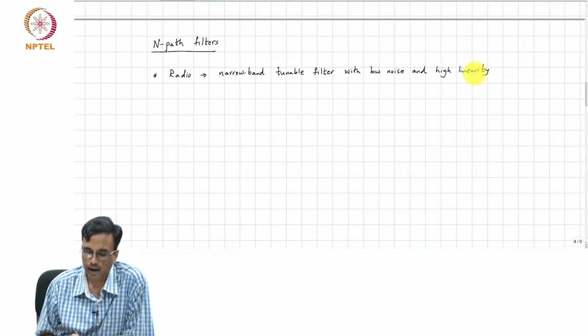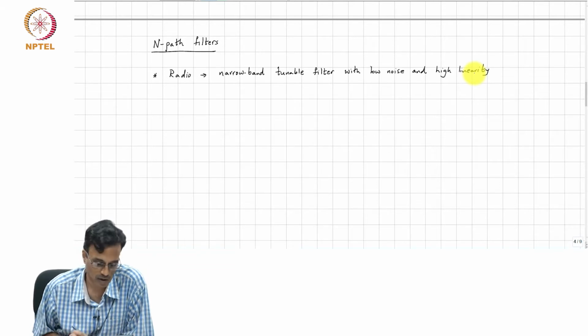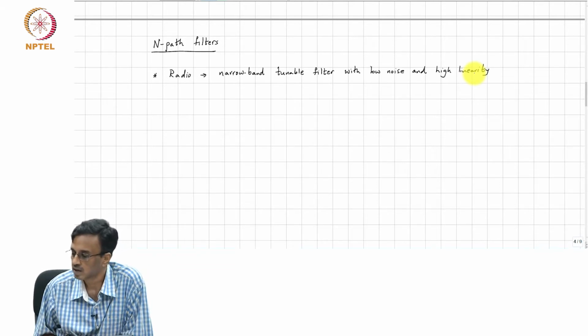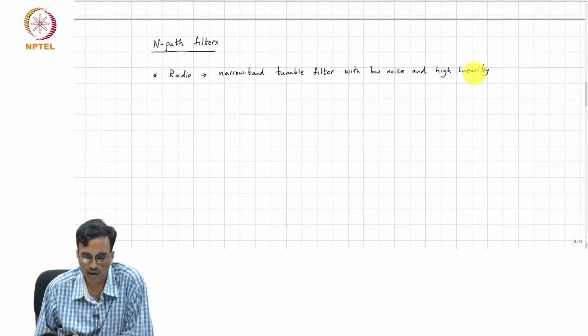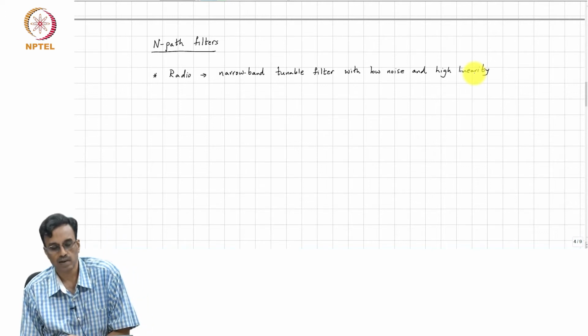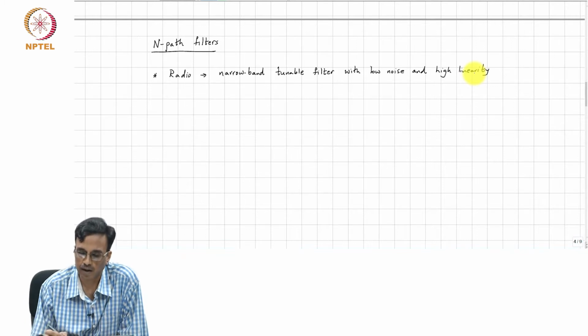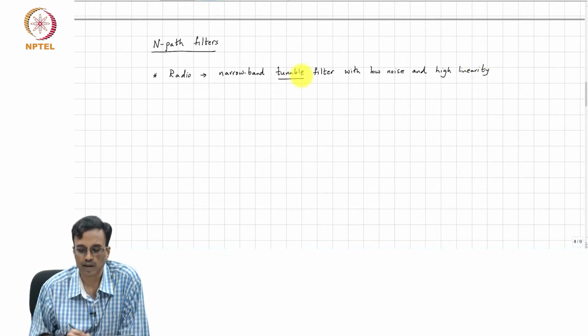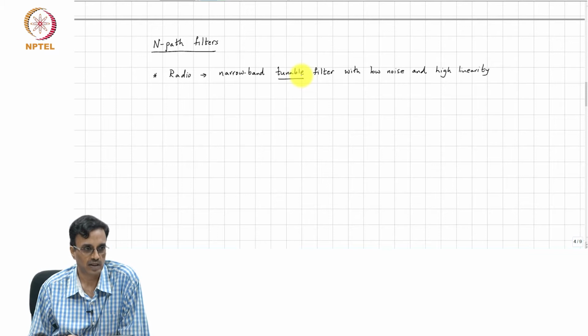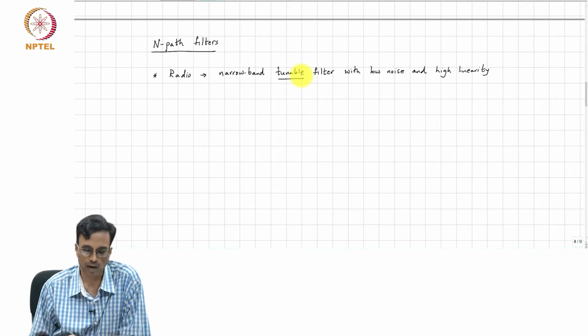Okay. And as we have discussed earlier, the use of inductors and capacitors to make tuned circuits was done in the past and is still done, of course, but they have difficulties making a filter that is tunable, because easily changing an inductor or a capacitor is physically difficult, right.